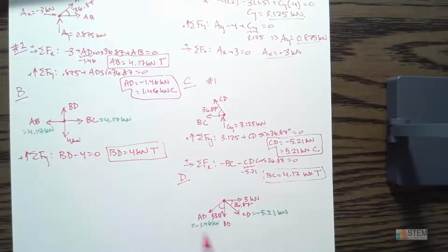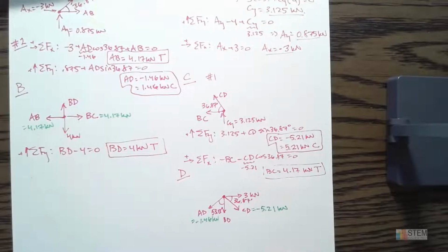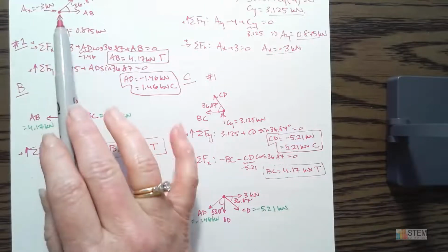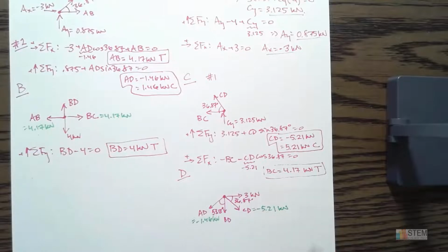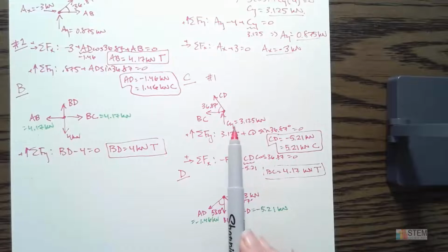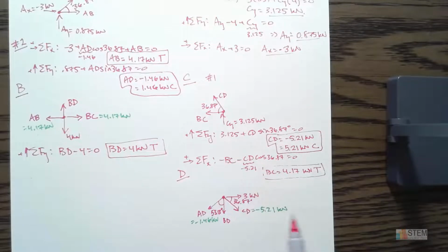If you want, you could use this diagram here to check your answers. So do your equilibrium equations. Once you put all the forces and everything in, the two equations should both equal 0 if everything's done correctly. All right. So hopefully that makes sense, the steps we went through. Just draw out the joints, each one. Put all your forces going out of the joint. Make sure you include these external support forces, like the pins and the rollers. And then just pick the one with the fewest unknowns, and keep doing that same kind of thing until you find all of your unknowns.